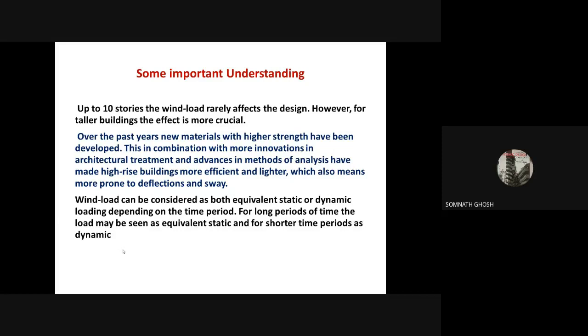And this wind load is a dynamic load. You all know the wind pressure is fluctuating with time, it's changing with time. It's a dynamic load. But you can treat the wind load as an equivalent static load. That means the dynamicity is considered, but ultimately it is presented as an equivalent static analysis. But that is okay.